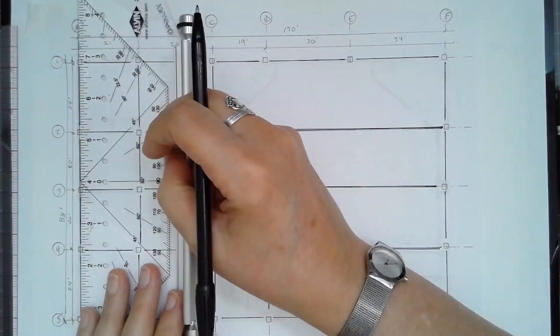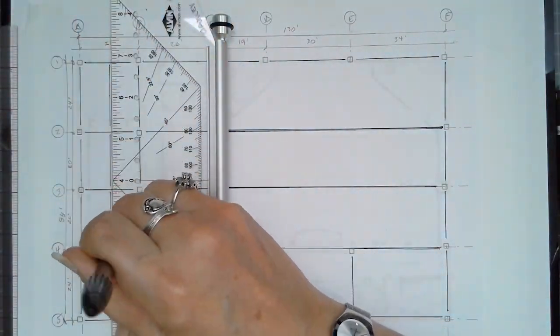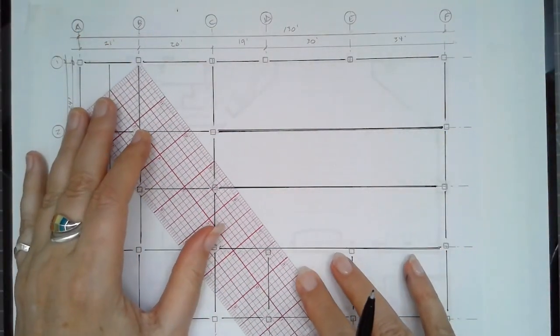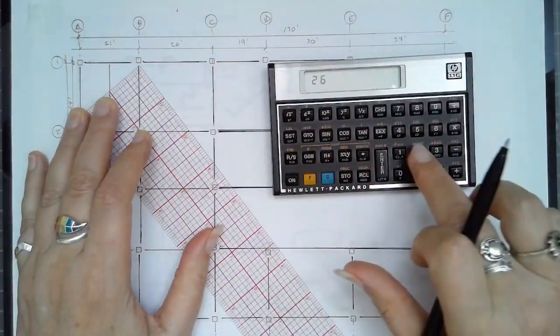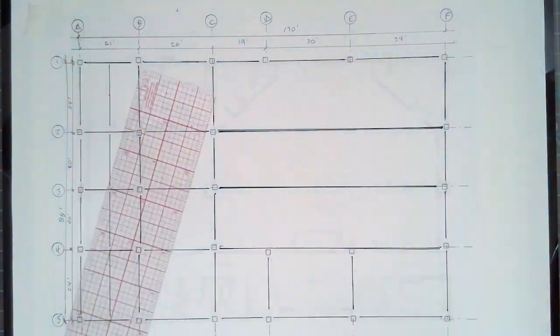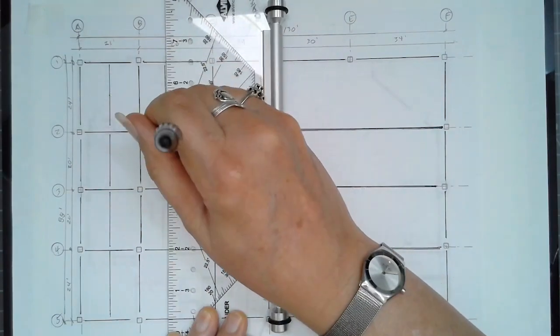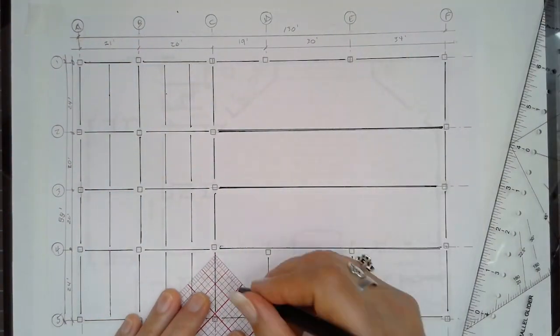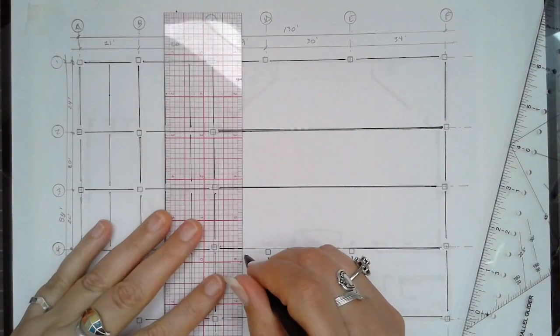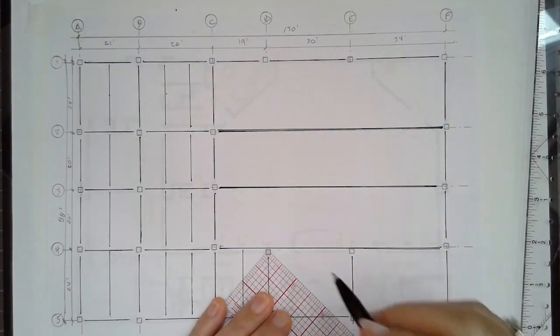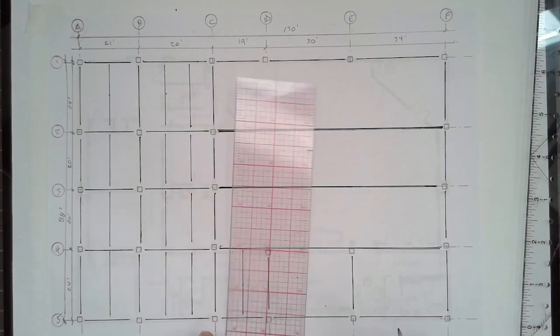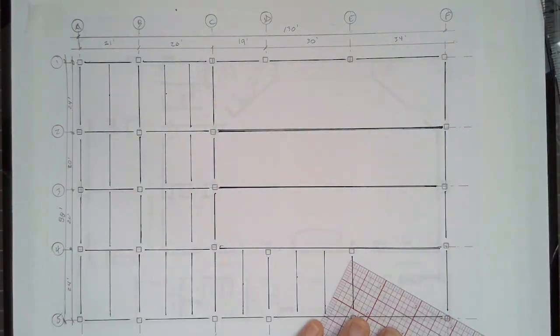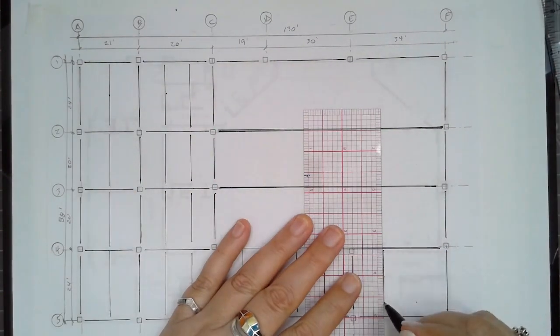Now here's a trick for you. When you don't know the exact dimension of something, to divide it in equal spaces, notice I'm tilting that ruler to thirds, and so that's actually splitting it up on the diagonal by thirds. That's a handy way to split an unknown dimension. I'm doing it here again on splitting in half, another into thirds, and then the last one also into thirds.